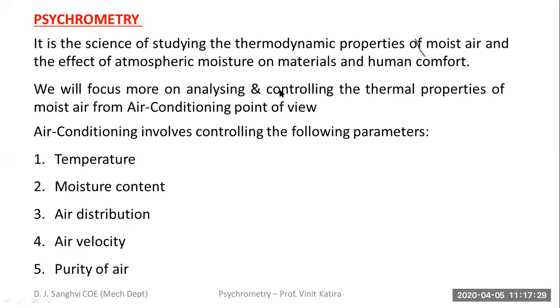Additionally, moisture is as such water vapor. Water vapor has a high amount of latent heat in it, and to control or to add or remove water vapor takes quite a bit of energy. So, it is very important to study moisture whenever we are doing air conditioning system design.